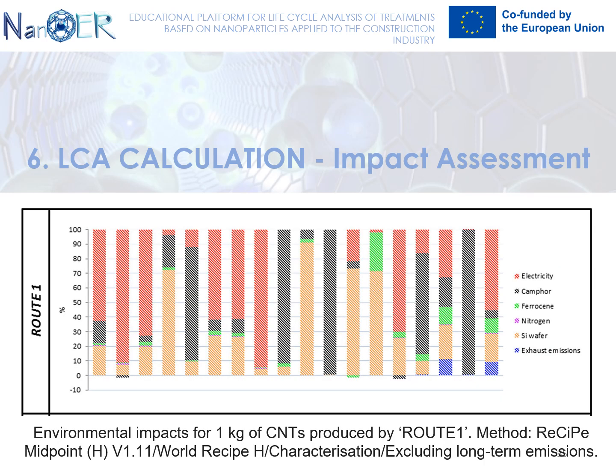Graph depicts the share of each contributor to the impact characterization results for the floating catalyst approach. The greatest contributor to CVD's environmental footprint is the electrical consumption in most of the categories. Generally, CVD is an energy-intensive process with heating requirements ranging from 480 to 9,100 megajoule per kilogram CNTs. In this case, the corresponding values are around 2,480 megajoule per kilogram of CNTs.